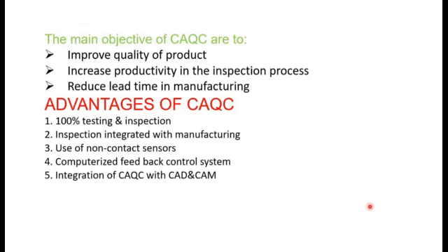Then the advantages of CAQC. It gives 100% testing and inspection. As computers are used in quality control, the productivity of inspection and testing is improved, and therefore 100% inspection and testing is possible here. Then inspection is integrated with manufacturing. As this is computer aided quality control, inspection is integrated with manufacturing, so it finds faulty products at the manufacturing stage itself.